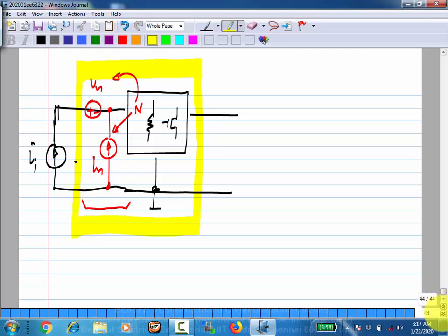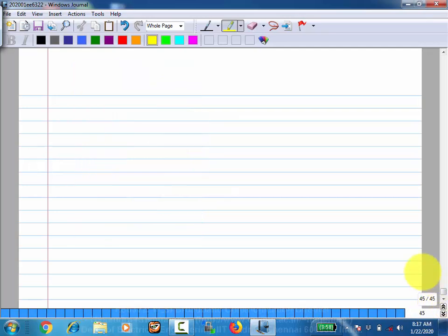So let's continue this for a couple of other components. Essentially, the lossless components like inductors and capacitors don't have noise associated with them. And then we have the other type of transistor, which is the bipolar junction transistor. It is not used as widely as the MOS transistor these days. By the way, the noise model for NMOS and PMOS is the same. You will still get 8/3 kT gm. It is just that for the PMOS you have to calculate the gm appropriately from each parameter. That's all.